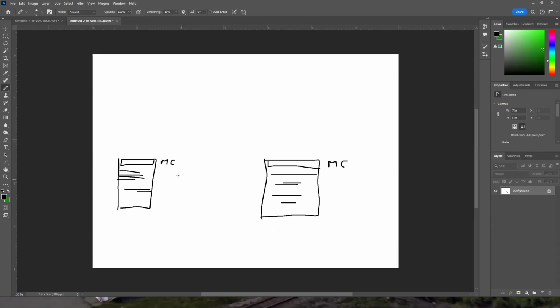Now, if this is a fiber optic line going between those two media converters, then this media converter is going to have to convert the electrical signals into light pulses, and this one will have to receive that and convert it back to electrical signal, so the network continues.